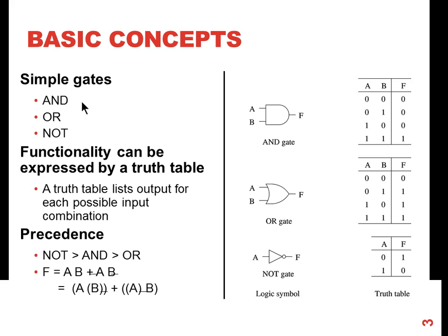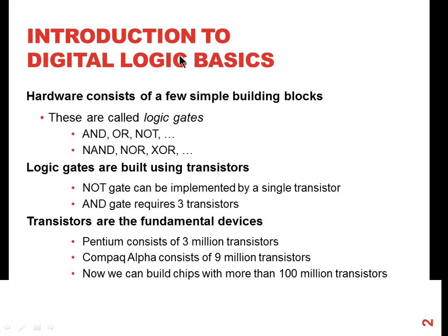As you might have already studied, ultimately when you do chip design and finally get something working on a chip, bottom line, everything is on transistors. With the current technology, everything is CMOS transistor based. Based on which technology you're using, there might be millions and millions, and right now a few billion transistors on a CMOS IC. So the gates that you see here are ultimately converted to transistors, and the transistors work on the bottommost part of the chip.